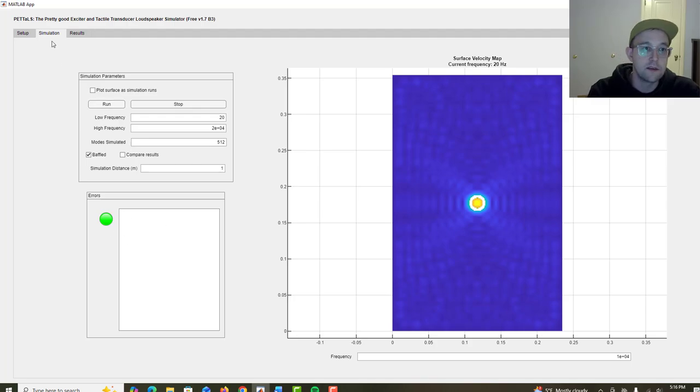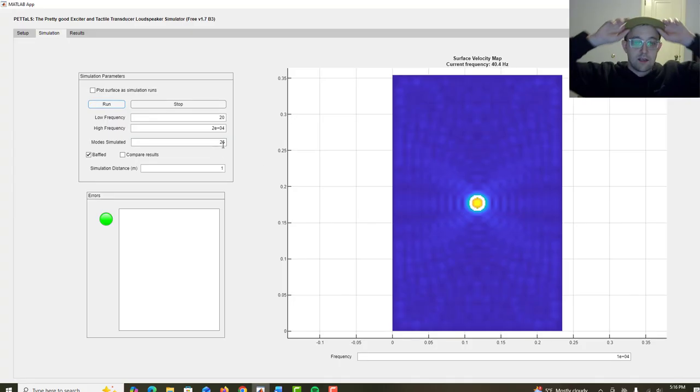So this setup is going to have 25 modes, so it runs. I at first tried making it 10 centimeters thick, which only had 11 modes, and it didn't run. So I redid the video. Now it's 5 centimeters thick, and it runs. So if for some reason you are simulating something like this that only has 10 modes and it doesn't run right now, that's why, because I haven't updated the error message yet.